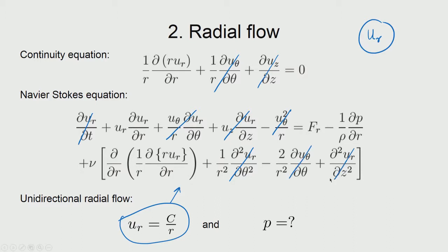So, you could already see that this is already satisfying. So, this would go off, but what you could see is that these terms would still survive. Which means that even if you want to drop this term, saying that there is no body force along the r direction, you can see that there must be a pressure variation as a function of r if you want to use a simple form of radial velocity like this. So, this can be immediately plugged in and you can derive it.